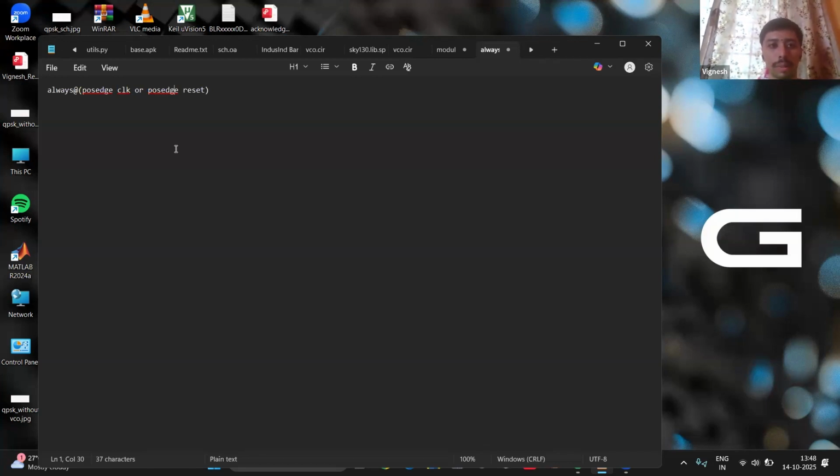if there is a zero input incoming, it stays in the same state itself. If there is any one input coming to the state, it goes to the next state. Whereas in the S1 state, again it will see for the 0 or 1. The output is one only when the sequence 101 is detected. So the output remains 0 till the sequence is detected. The output is 1 only when the sequence is complete, 101 or 100, like that.